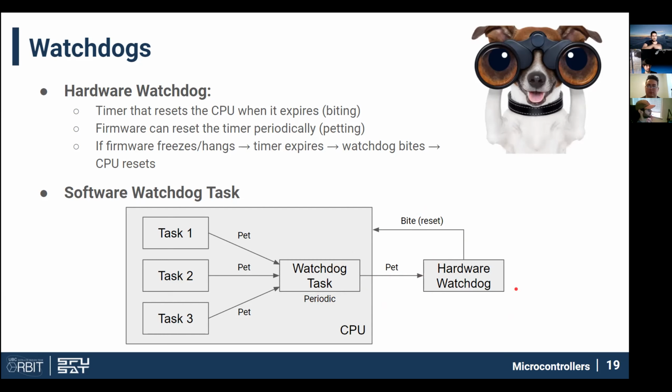So what those jumpers are is you can disconnect the jumper and it just turns off power to this, and so that way it can't reset the CPU. If you're debugging something, you generally will want the watchdog disconnected so that it doesn't reset in the middle of your debugging session. It's a good question. Thanks, Rodrigo.